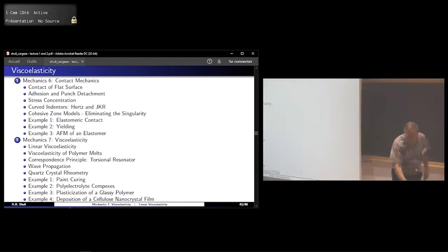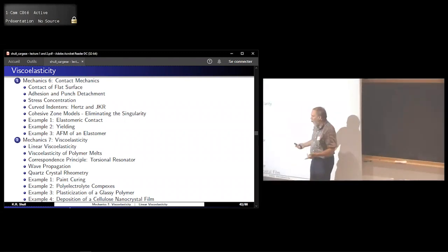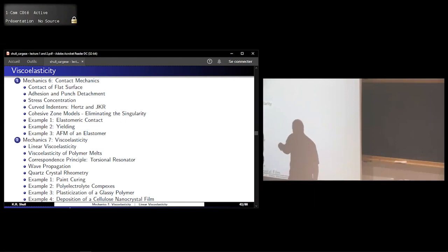So like the last time, there will be some introductory stuff, basic viscoelasticity things, and then some examples of a correspondence principle. Every field has their correspondence principle, but in this field, what I mean by it is if you know the elastic solution to a problem, and it's the same loading, but it's an oscillatory loading, then you just replace the modulus with this complex modulus. So we'll talk about that a little bit.